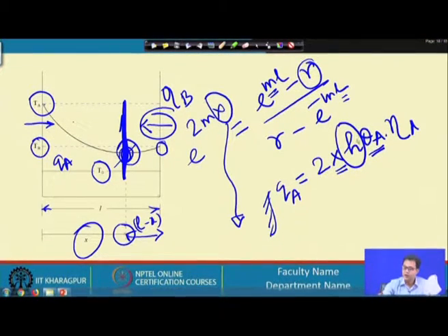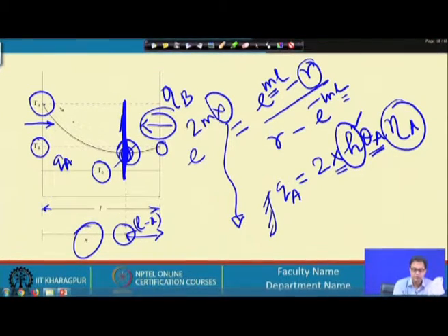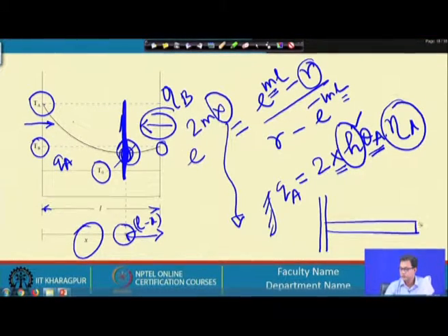Then the heat transfer coefficient is h, and this eta A is taking care of the fin connected between this wall and this length. This is the adiabatic condition prevailing at this location. So, this is at theta A, and this fin temperature profile we already know. But what is the length? This entire fin is not at theta A. So, what is taking care of that?